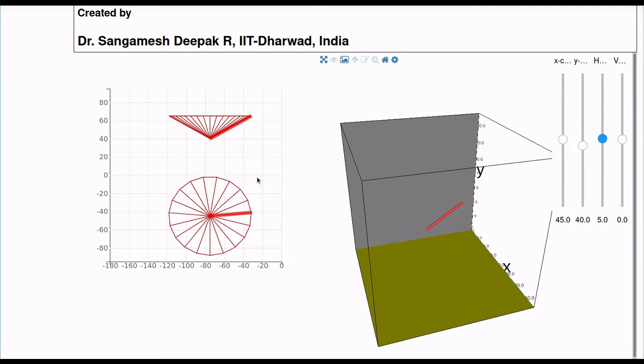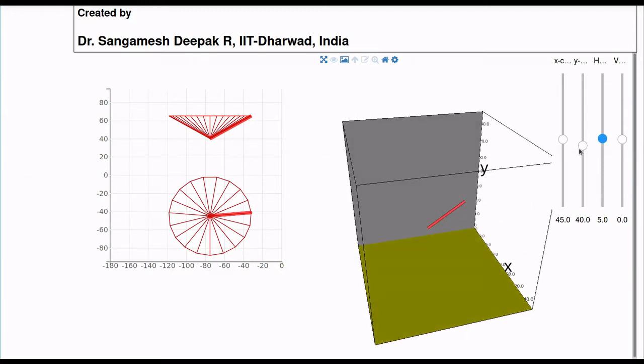Okay, all right. Now we start giving the rotation to this line about an axis that is perpendicular to HP. So that we can just see that indeed this point B here moves along a circle, and the projection of the point B in VP would move in a straight line. We call that not point B but point B1. Okay, so the projection of point B1 in VP would move in a straight line, and the projection of point B1 in HP would move in a circle. So let us just see this.